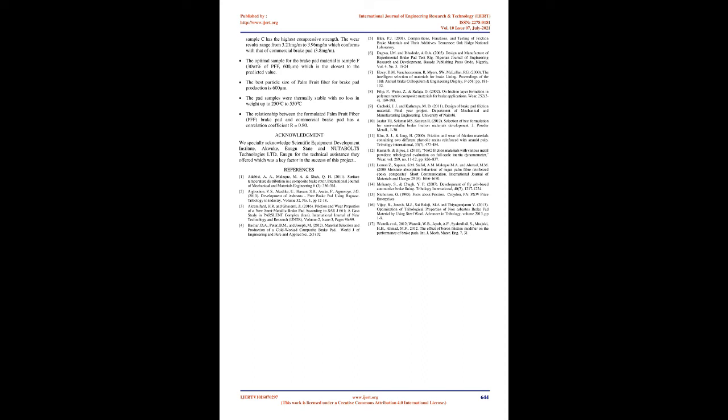V. Conclusion. A non-asbestos brake pad material using palm fruit fiber as base material was developed. Various mechanical tests were conducted on the produced samples and their results analyzed. The results related how the samples performed during testing. The following were deduced from this study. The hardness values of the samples, which range from 94 HRB to 104 HRB, are in close proximity with the commercial brake pad.